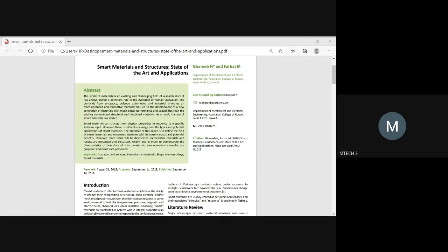In the beginning, they produced products called audio transducers, for direct connection with electrical circuits. They developed small piezoelectric igniters, right? They also used piezoelectric filters, basically for radios and TVs. Initially, we used to have big TVs, right? In all those, they used these piezoelectric filters, and the TV remote control that we use consists of ultrasonic transducers. Even these transducers could be made up of piezo elements. So these are the applications wherein it was used long back, since 1970, after the World War II.